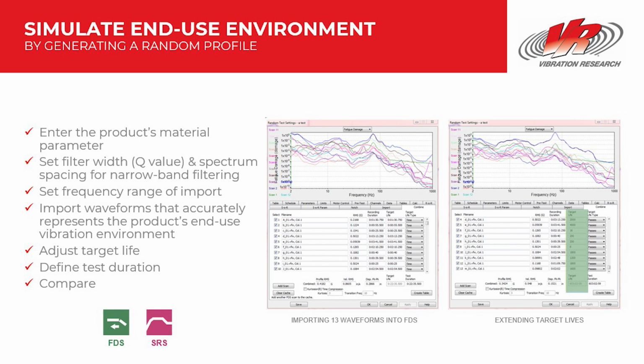The shock response spectrum package in vibration research software is then used to confirm that the vibration test is not overly accelerated so that we do not generate foolish failures or failures that possibly would not actually occur in the field.